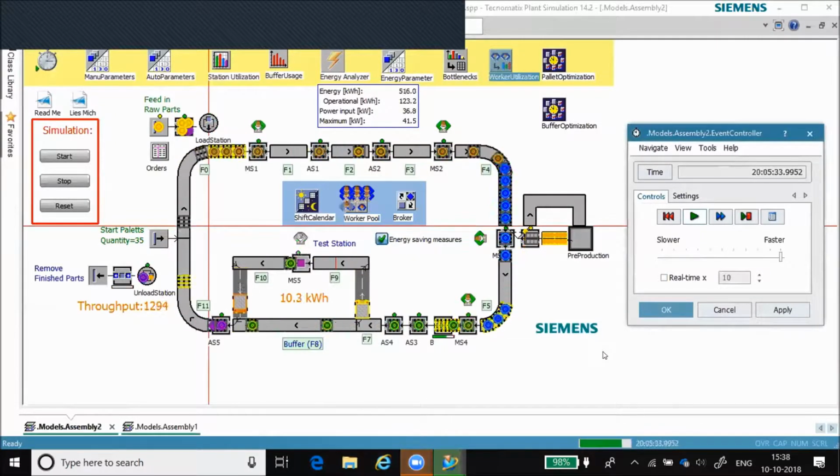So typically when it's a greenfield project and you want to optimize a particular line which has too many constraints, and you have existing data from the line itself, you can put in all the data, run it for a month, and analyze what is actually going wrong and how you can optimize it. Because probably the line might be doing well on one particular day for a particular variant, but if that variant changes for a different plan, then you can run it for the whole month and check how my particular line gives me optimum output for different kinds of variants.